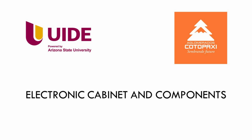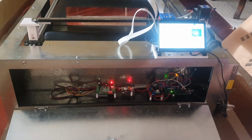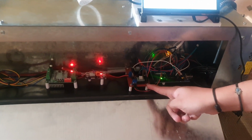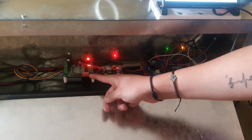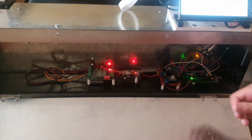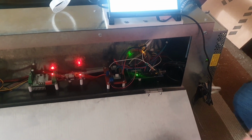So let's go ahead and take a look at the explanation of this part of the project. In order to keep the elements organized, I decided on a small cabinet that is used for the storage of the electronic components. Here we can see a CNC shield specifically designed for this project that controls the NEMA 17 stepper motors for the camera mechanism, a NEMA 33 stepper motor driver that controls the conveyor belt system, and an Arduino Mega that receives the signals coming from the Raspberry Pi and gives them to the motors in general.